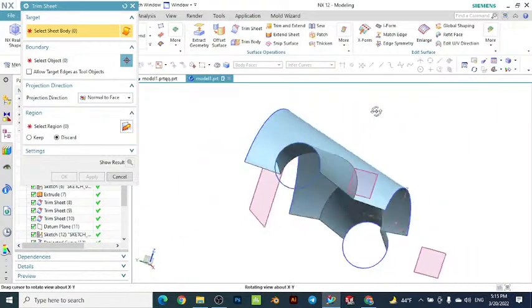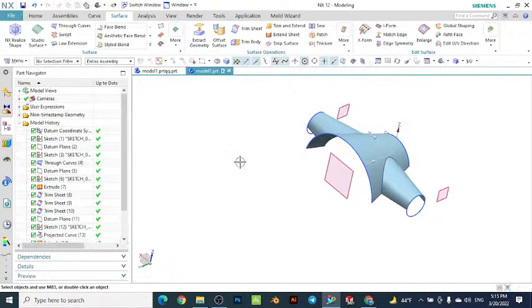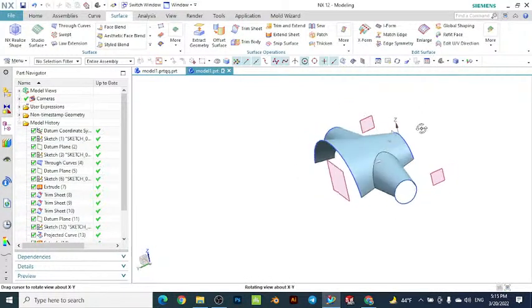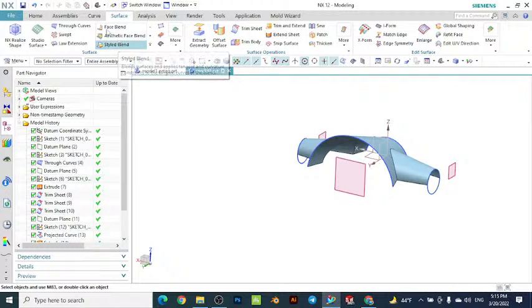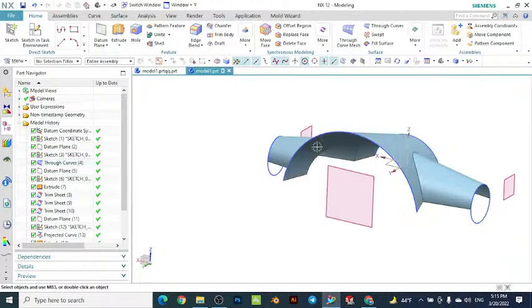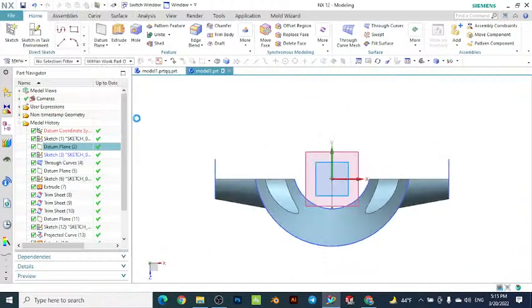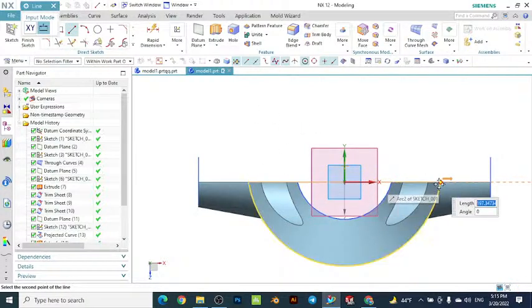Here we obtained such a system. Now what we have to do is close the trim sheet, and make some closing elements. In order to do this, we will use several options. Let me make the first option. I would like to close this part, this arc. I can use the sketch, select this plane and press OK, and draw a line between this point and this point.